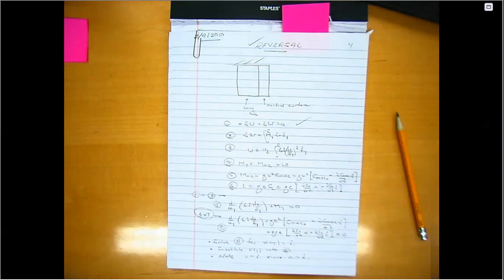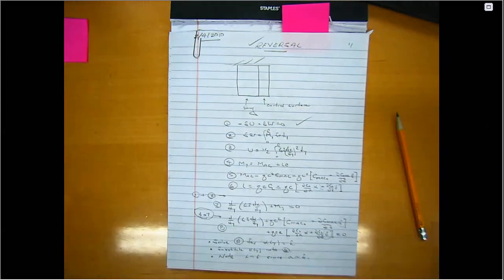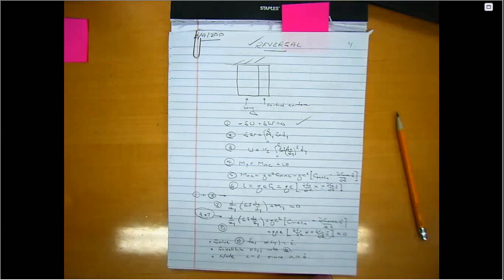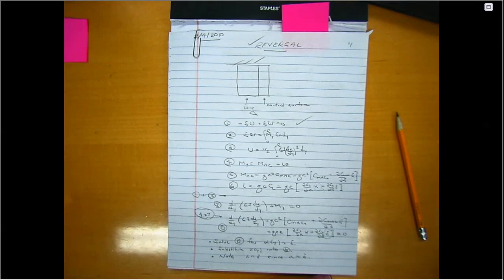But, you know, if I integrate the lift over the entire wing, I'll get some constants, which involves the dynamic pressure, by the way, times delta. Now, I want to know when that total lift is zero, which is when the coefficient of delta is zero, right? Because it turns out within the framework of a linear model, reversal occurs at a certain q, and it doesn't depend on the size of delta, since it's a linear model. If it were a nonlinear model, it would depend on the size of delta. But that's research.